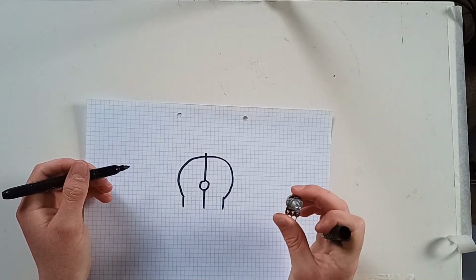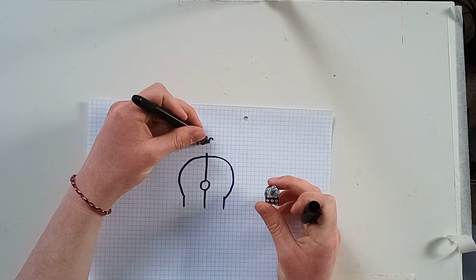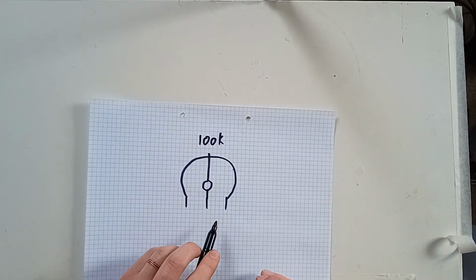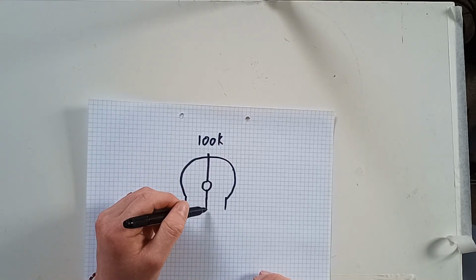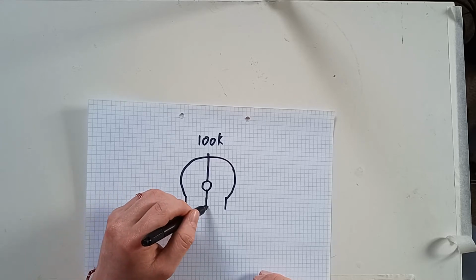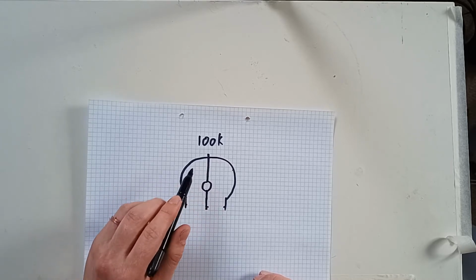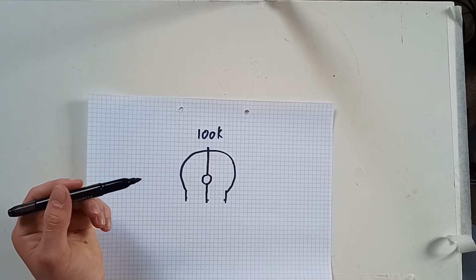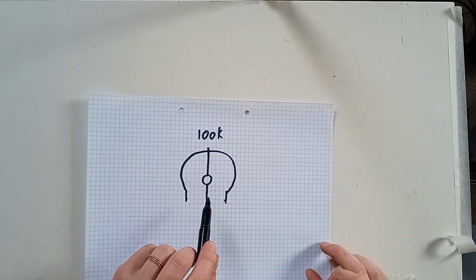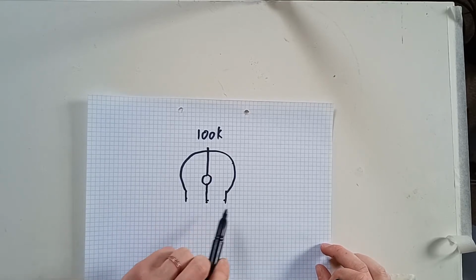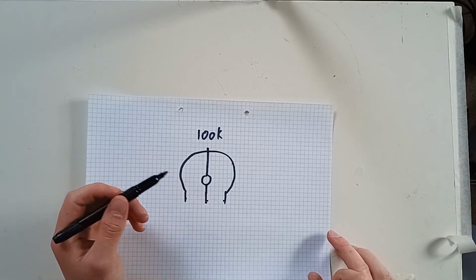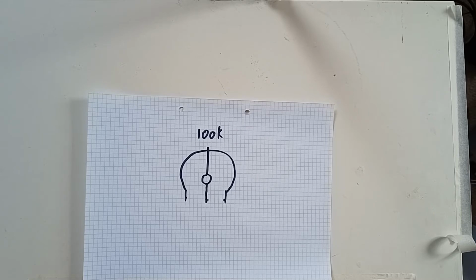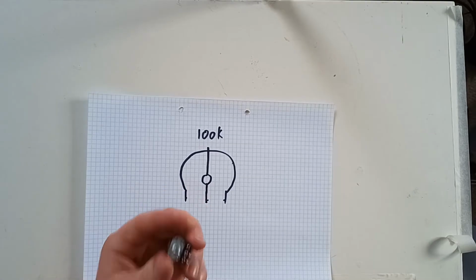So in the case of this potentiometer, it has a total resistance between these 2 pins of 100 kiloohms. The wiper then moves along the track, giving a different resistance between these 2 pins or these 2 pins, depending on whereabouts it is positioned on the track. A dual gang potentiometer, you have 2 of these tracks that are isolated from each other completely, and isolated wipers, which are just stacked on top of each other. So it allows you to control 2 different things with just one control.